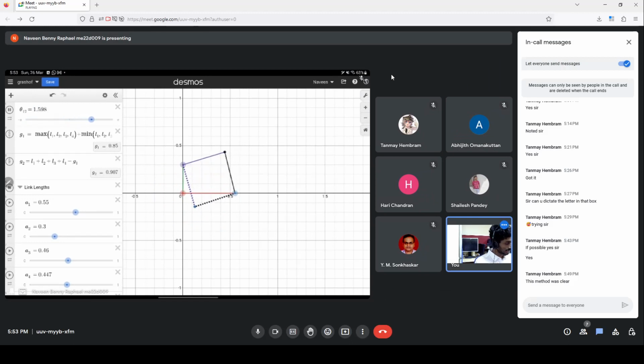So the green is once again doing a full 360 degree rotation, and therefore, anytime we have a link doing a 360 degree rotation, we call it a crank, because many of our actuators are rotary actuators, and they are able to provide energy to the system through a rotational mechanism. Therefore, the green section is called the crank. The black link in this case does not do a 360 degree rotation. Instead, it just rocks around, and therefore this is called the crank rocker mechanism.